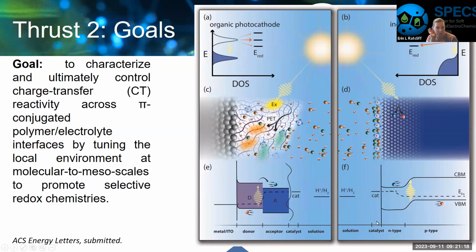When you take a conventional semiconductor and interface it with an electrolyte, there's a very discrete boundary, and the energy levels will pin to the Fermi level of the redox molecule. But does that happen in organic systems, and can that happen if we have blends of donor and acceptor in order to dissociate the exciton?